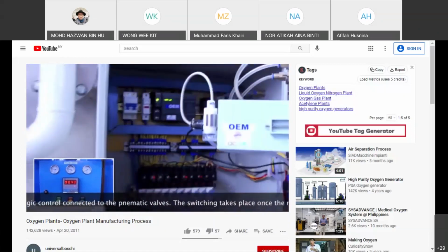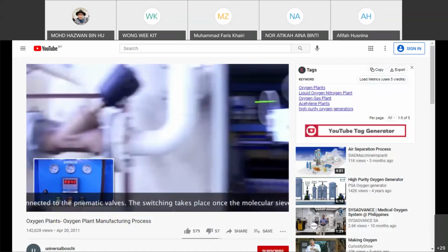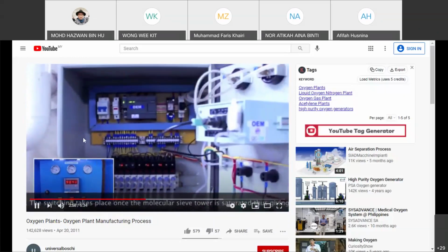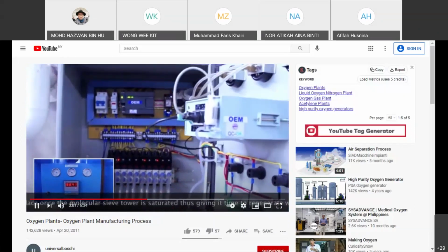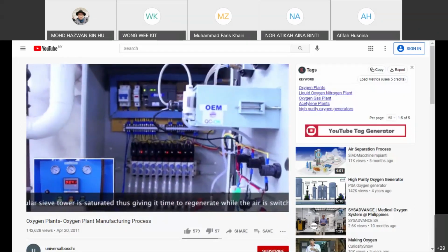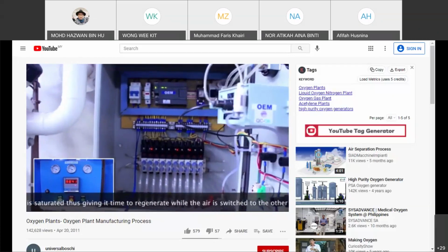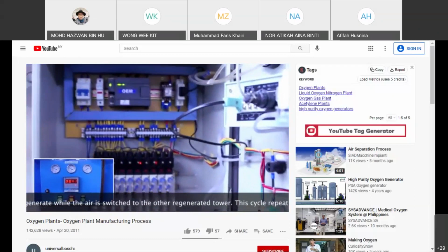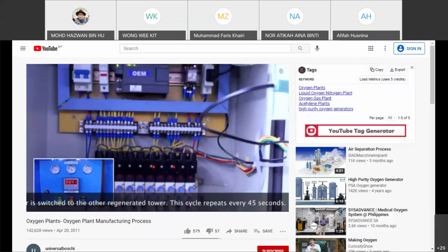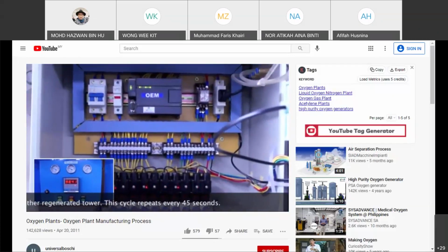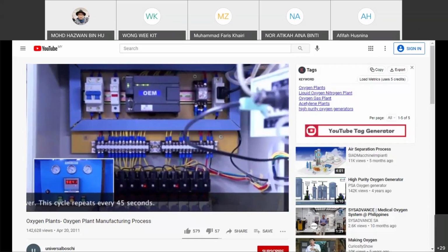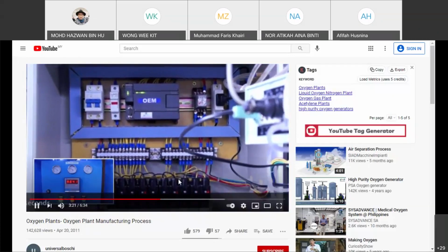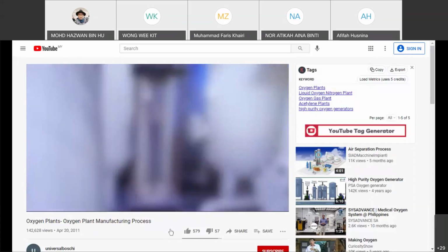Right, so this is connected with a controller. The controller controls the valve to ensure that when the gas goes into the column, it does not go in directly but in stages. First you charge the gas, and then it goes to the column, and the pressure is slowly applied to ensure that it goes into the absorber and the absorption process occurs smoothly, without damaging the column. It says that the process is repeated every few seconds.